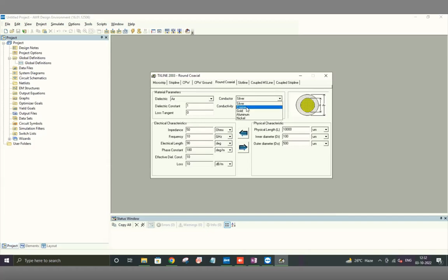You can just leave that for now. Sometimes you can actually just specify the conductivity as well. That's what changes as I go from, say, copper to silver. This number changes. In our lab, we often work with superconducting materials, and there's no specification, so I just make this conductivity some very large number so that it doesn't affect the loss part. Because it can have a very small effect on your characteristic impedance if you're not in the lossless limit. Anyway, this is one of the important things.